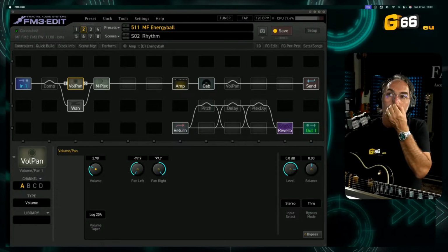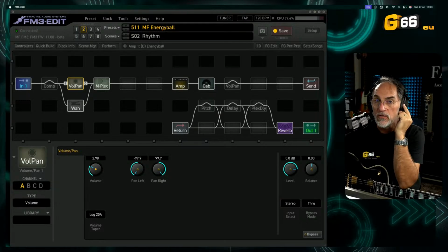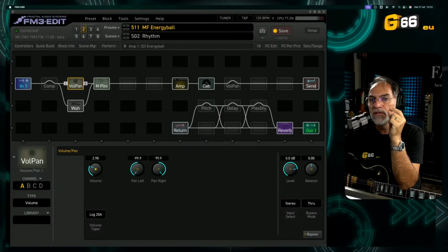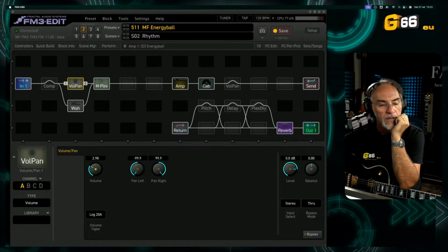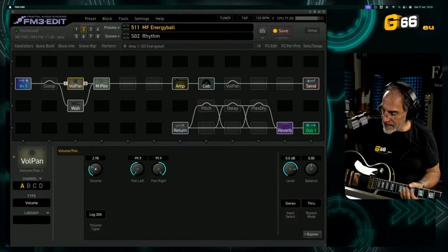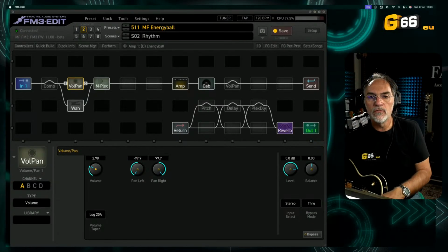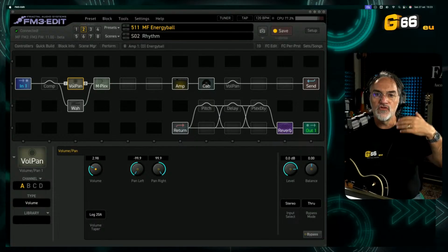The effect of the volume in this position is exactly the same as the guitar, but you have a big advantage. Do you know what a treble bleed circuit is? It is a circuit that some luthiers put into the electronics to avoid the treble frequencies being attenuated when you go down with the volume.